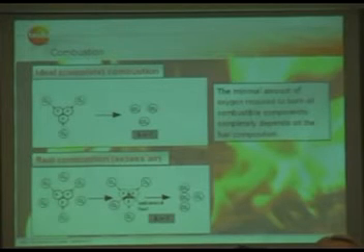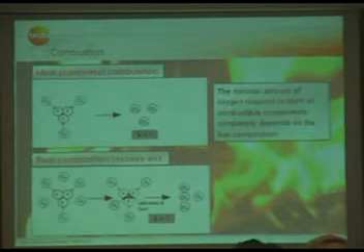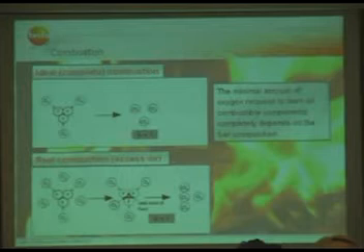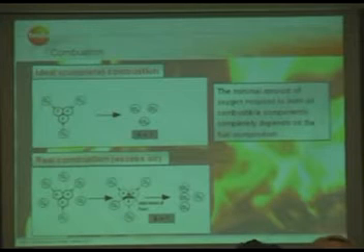If this is taking place, we are talking about stoichiometric combustion, or lambda equal 1. That means the actual needed air in comparison with the necessary air to burn all the fuel completely. But usually that doesn't work in the real world.